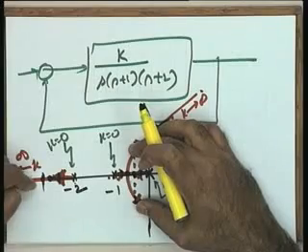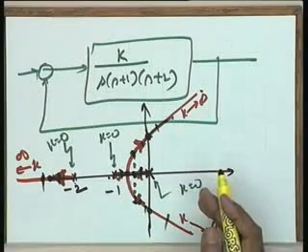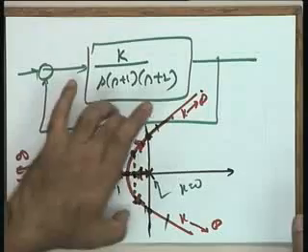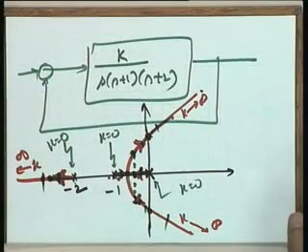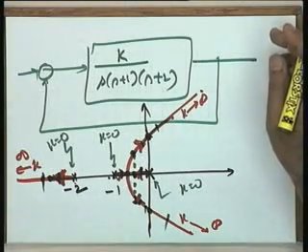Okay? I hope it is clear that the third root is also given by the third or any number. In a higher order system, it will be more than 3. So, those roots other than the dominant roots also have to be investigated and the dominance conditions examined. If it is satisfied, you are happy. If not, then you have to suitably re-enter the design cycle so that the effect of the roots other than the dominant roots is accounted for. Okay?